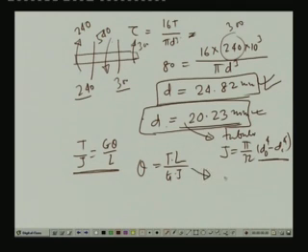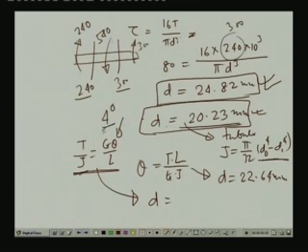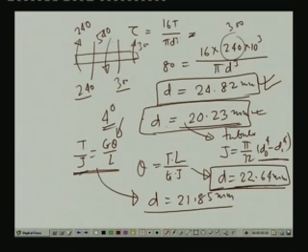From this, if we compute d for the solid case, we get d as equal to 22.64 millimeter, and again for J of the hollow one, keeping theta limited to 4 degrees, we get d as 21.85 millimeter. In this particular case, as you can see, the diameter 22.64 is again the governing one. So, in the first case we had 24.82 millimeters as the diameter to be provided, and in this case we have to provide 22.64 millimeter to resist the twisting moment through the gears as shown.